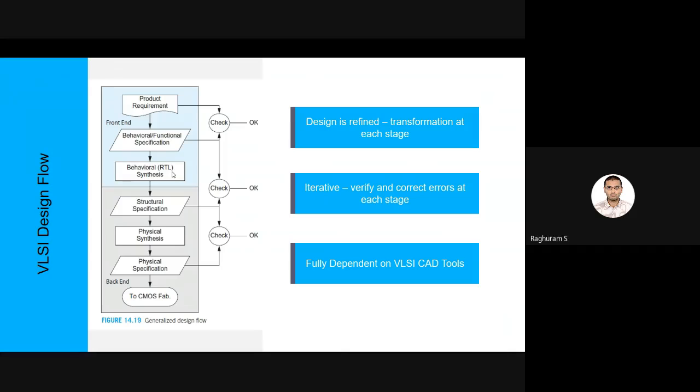One of the most important design requirements of Verilog is that it should, as far as possible, be similar to higher level programming languages like C or Fortran of that time, etc. So it's easy to code in Verilog, but you have to remember that you're not coding with variables, you're coding with digital logic. So that is one of the most important things about Verilog. It has many functionalities from high level programming languages, but they are applied to bit type data, to bit widths.